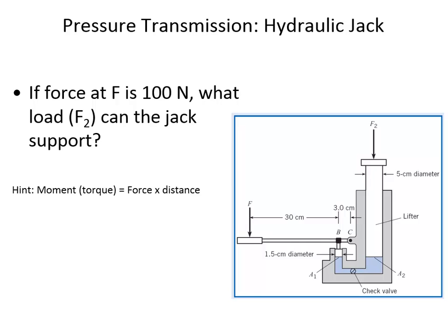But I've got the strength, obviously, to split big logs, but this thing is constantly leaking fluid. I have to always be pouring in more and more hydraulic fluid, because I think probably why they said not to put more than 6-inch diameter logs is you need so much force to split the big logs apart that whatever seal they have in the jack, because this log splitter is actually just a jack like this. You're pressing on the jack and it's pushing this log into a wedge to split the log in half.